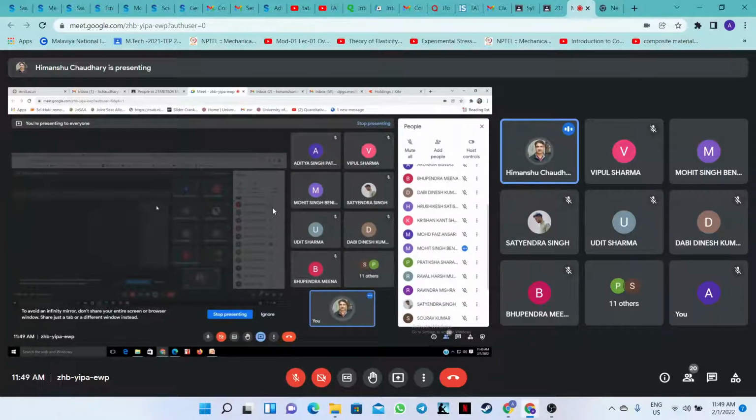The position of a link is defined by two motions. One is translation, the second one is rotation. So the position of each link is defined by rotation and translation. Rotation is given by a line drawn on it, and position by any reference point on it. So these two pieces of information are needed to find the position of a link. Independent parameters means one parameter is not determined by another parameter, or we are not expressing one parameter in the form of another. Then it is known as an independent parameter.